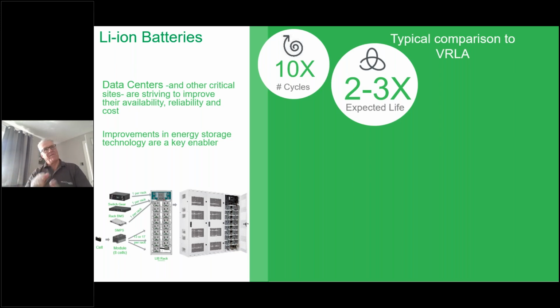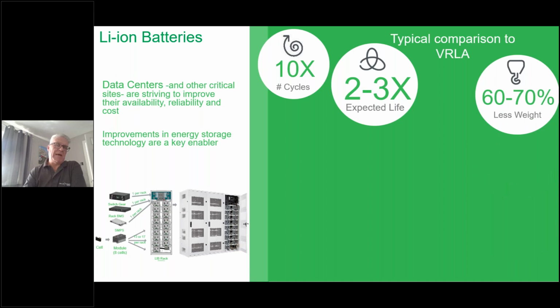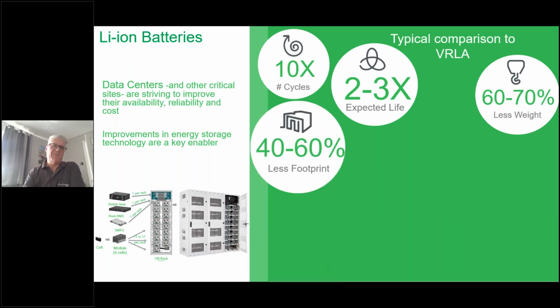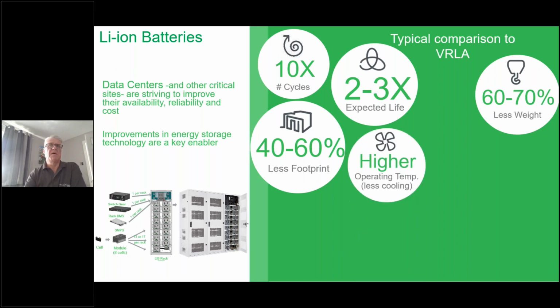The expected design life for your lithium-ion could be 2 or 3 times more than that. It has less weight, which matters with big battery systems, because there's always a question about the floor loading and how it can be supported. It's less footprint; they're more compact. This is only a small picture, apologies, but you can see a number of batteries sat within a normal floor-standing cabinet, and we'll have a number of those together supporting the UPS as need be. But certainly footprint is often a consideration.